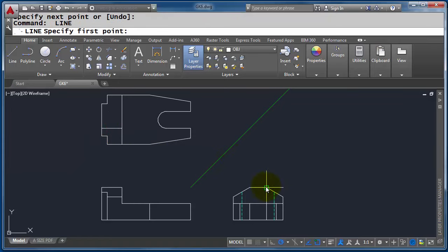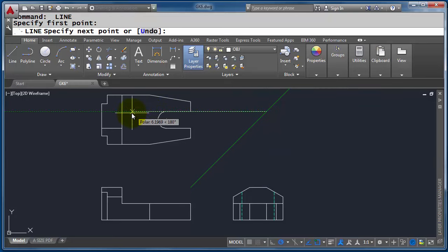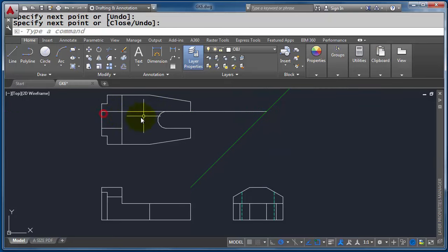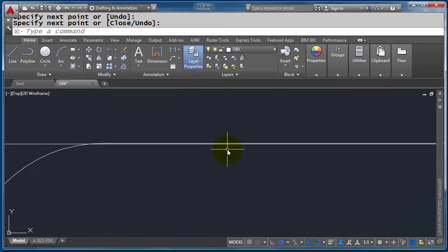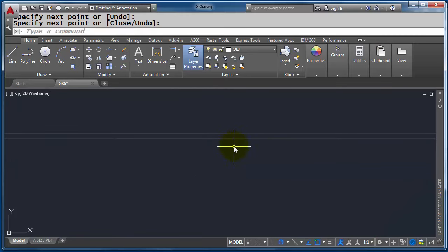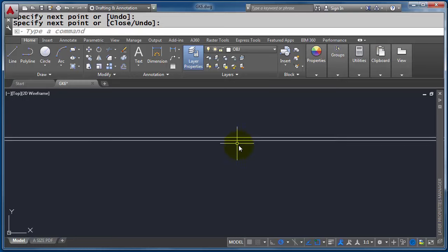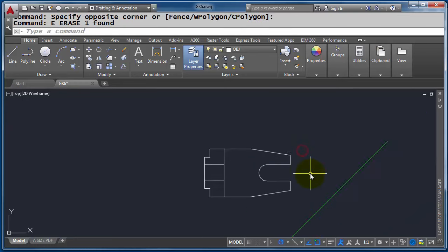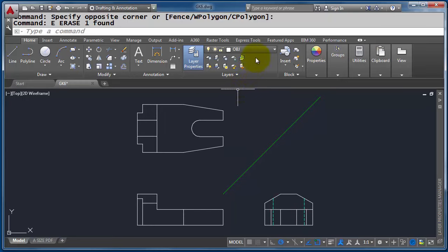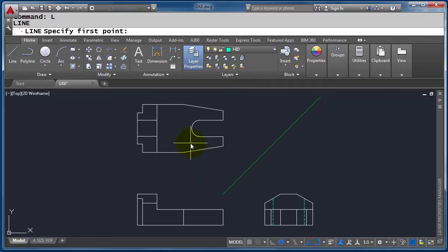With this one, I'm going to draw it out with an extra line segment so you can see what I mean. It's very easy to assume that these lines have the same width. They don't. They're different features with different dimensions. Switch back to my hidden layer now. I'm going to track the hidden edge down from that notch.